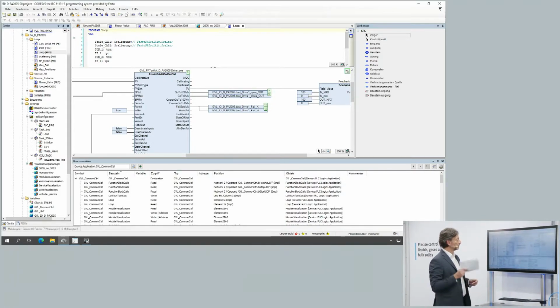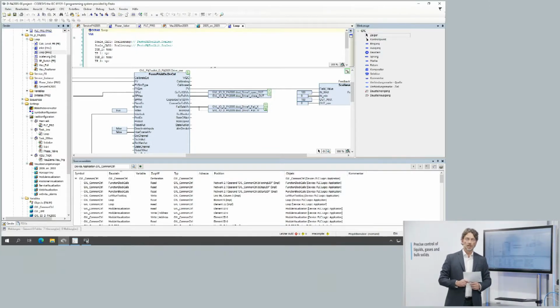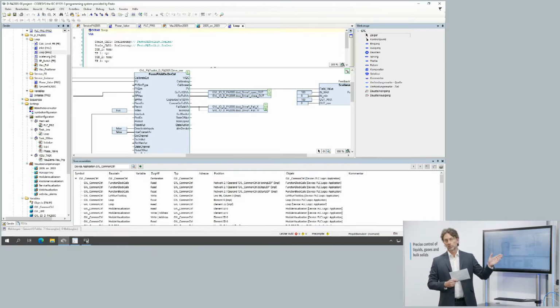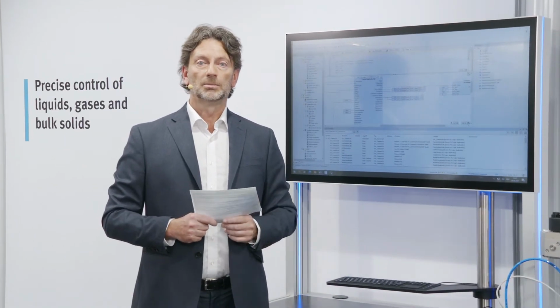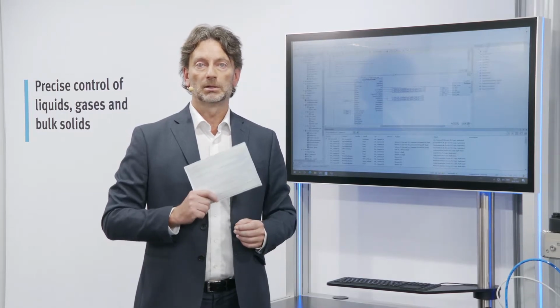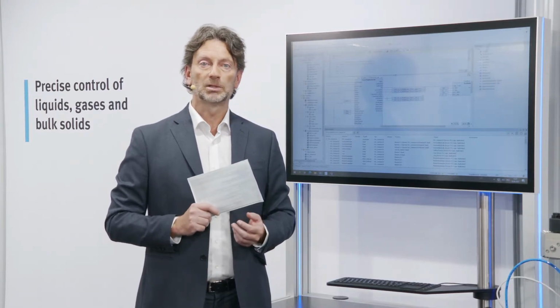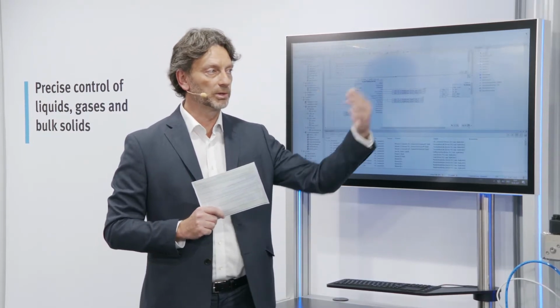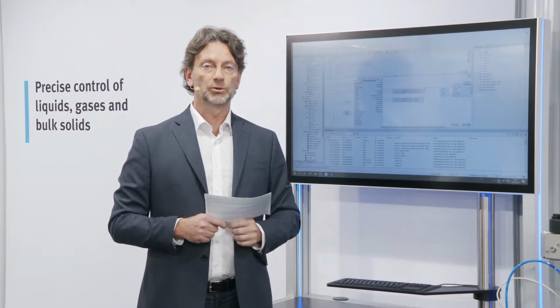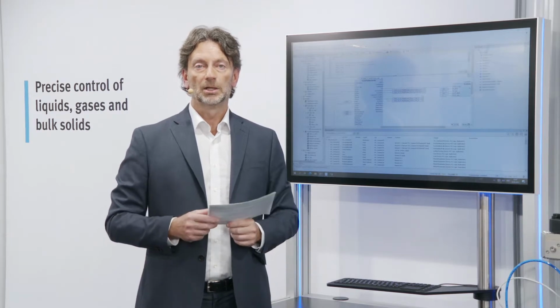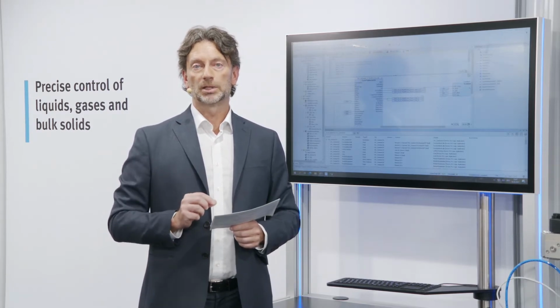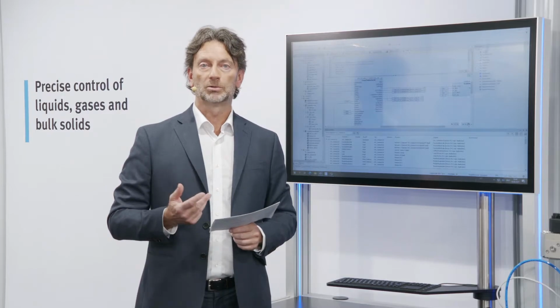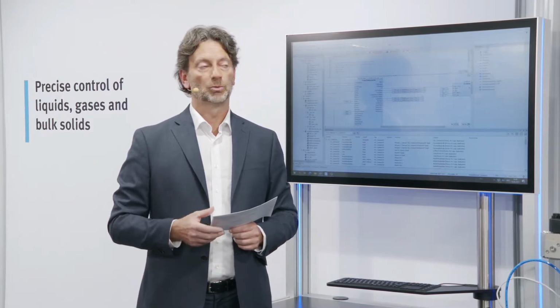And you mentioned before the services. So I told you that when we are talking about a remote I/O in a classical way of speaking, the main controller is doing the whole job. So the main controller is the one opening and closing the valves, talking to the positioners, and so on and so forth. Well, this is not really required anymore when we are speaking about modular production, where we are speaking about MTP.